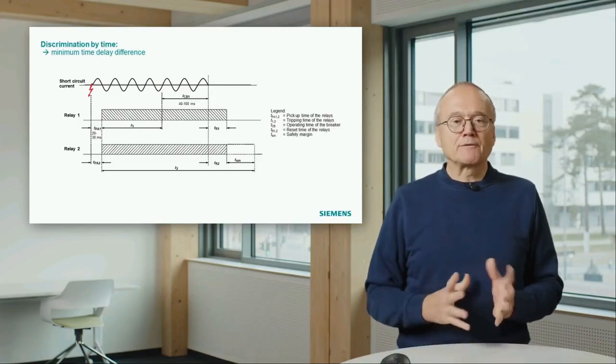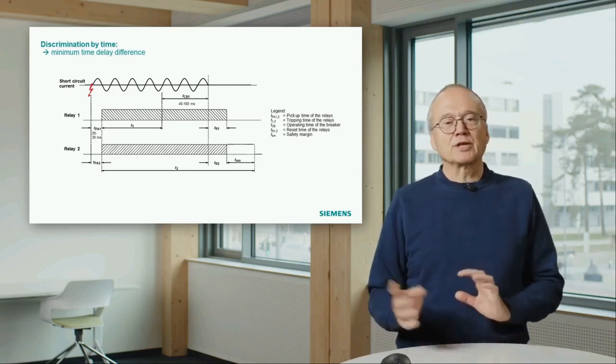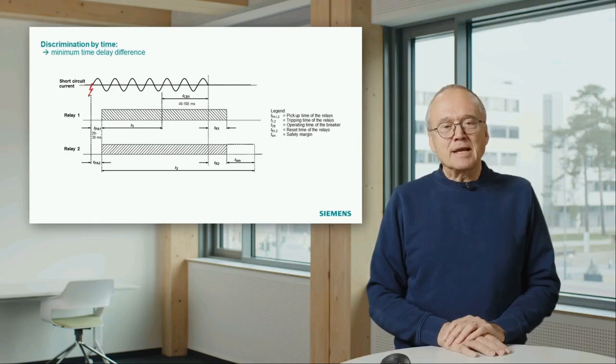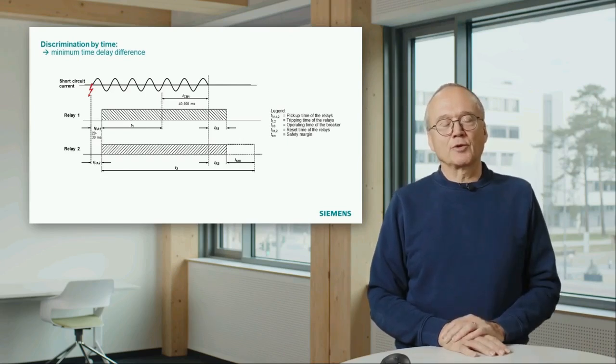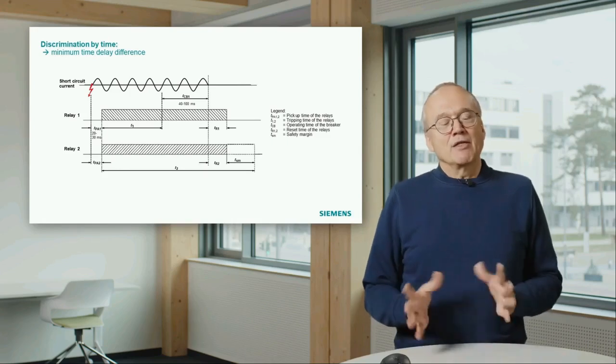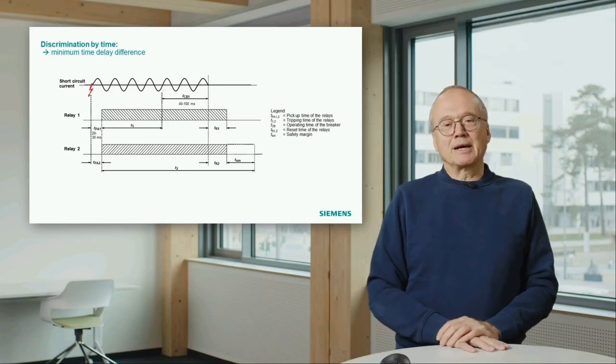And if we have something in the range of 40 to 60, 70, 80 milliseconds for the circuit breaker, maybe 20 milliseconds for the reset time, then there are some other reasons to have significant margin there.